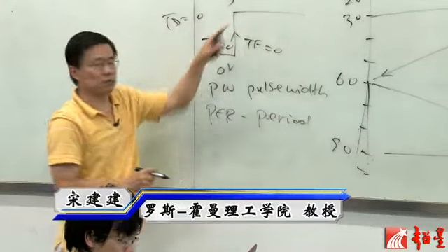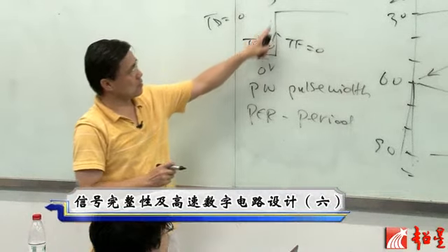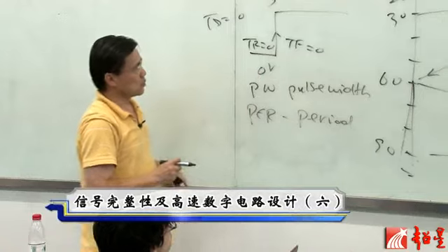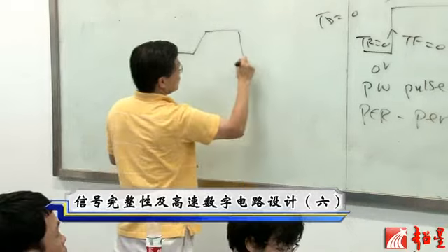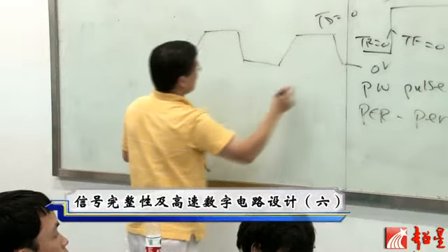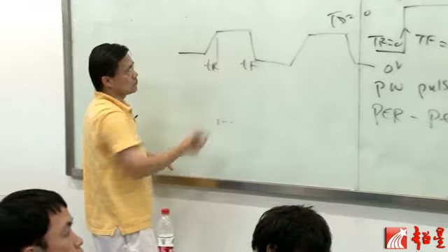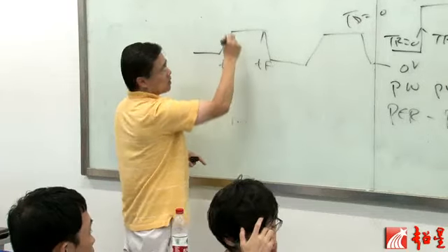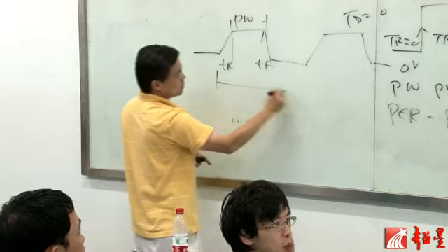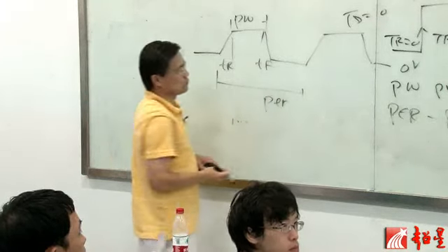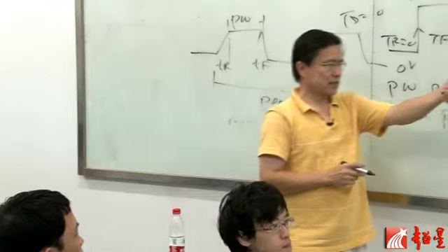So you basically have a pure mathematical step. There's no delay anywhere. Actually you can use this function to generate a square wave. To generate a square wave, you have rise time, fall time, then you have a pulse width, and then you can set the period. So this way you can actually generate a square wave. And that's this source.